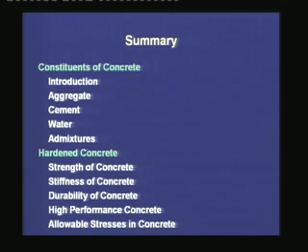The second property that we studied was the stiffness of concrete. Now, the stiffness of concrete is quantified by the elastic modulus. We need this quantity when we calculate the deflection of members. The calculation of deflections becomes important if the member is of smaller depth and longer span.